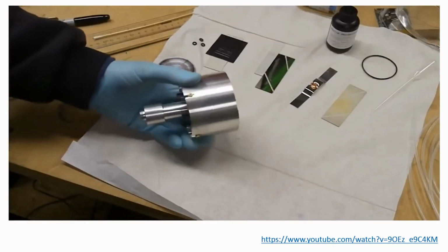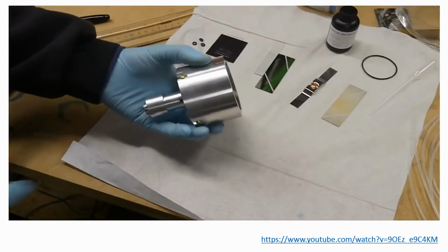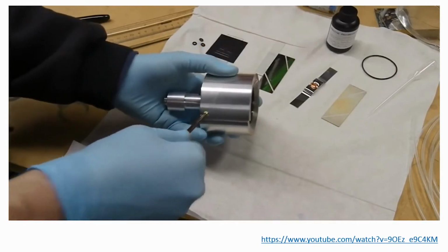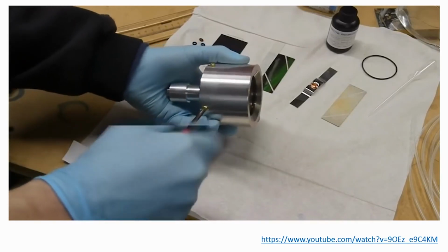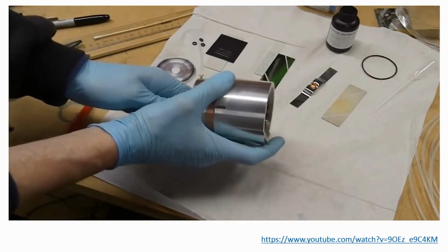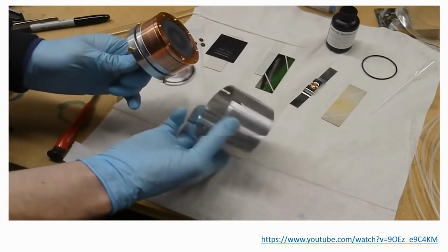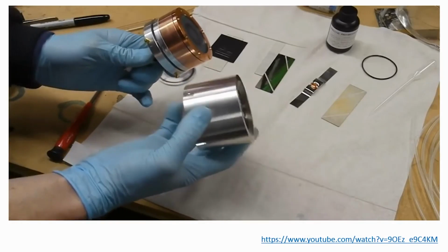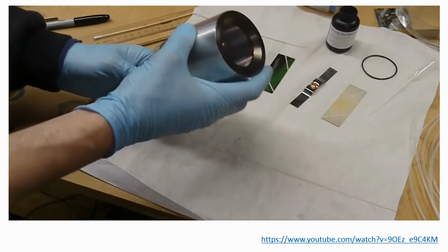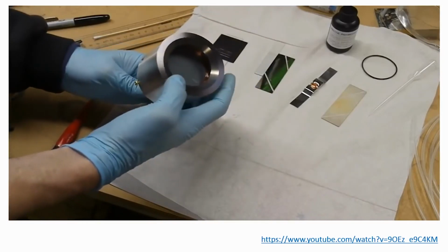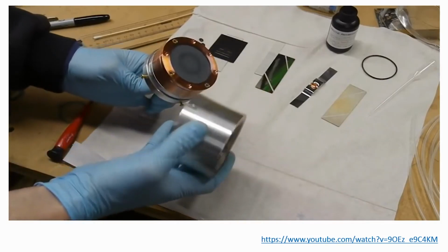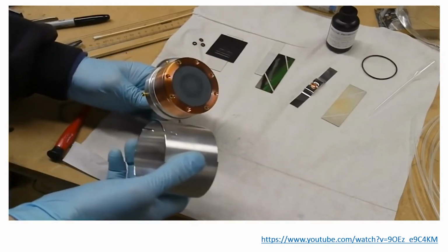The sputter gun itself is relatively simple in construction, so let me just take it apart and show what's inside and then describe how the whole process works. So the very outside is called a ground shield, and it slides off like this. And the purpose of this is just to keep the things that you don't want to sputter inside this. So when the shield is on, the only thing that's exposed to the chamber is the surface of this disc here, which is the thing that we want to sputter, to send off onto the microscope slide.